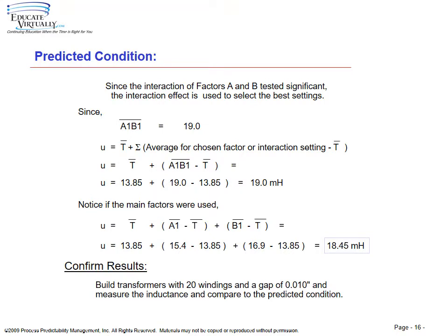Now, to confirm the results, we would build some transformers with 20 windings and a gap distance of 10 thousandths, measure the inductance, and compare it to the predicted condition. That validates and verifies that our design experiment has been successful.